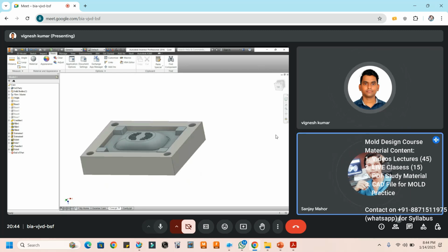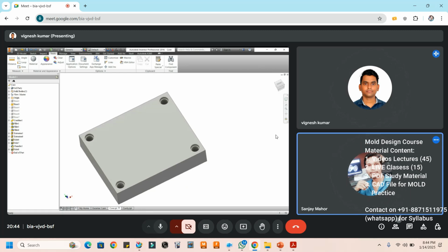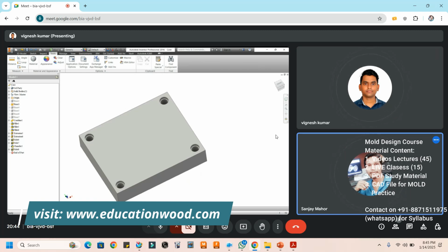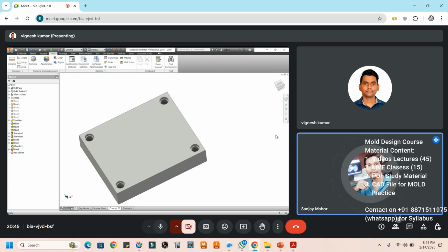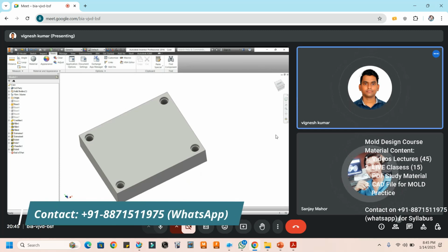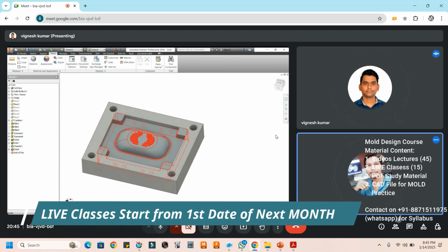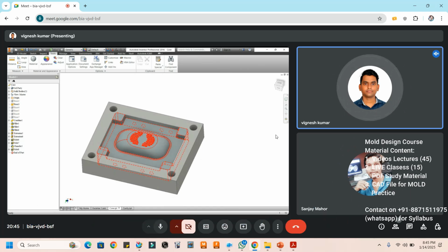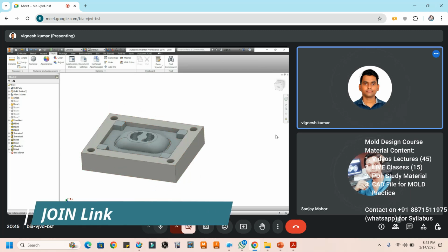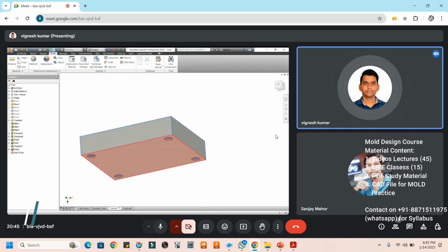From the top we have to provide the vertical channel, and that vertical channel will be connected with the vertical channel of the core inside, and then the vertical channel will become the horizontal line, and that horizontal will continue. Between the core housing and the core insert we will use an O-ring to prevent leakage. So the vertical cooling channel will be at 90 degrees with respect to the face, somewhere around 90 degrees.